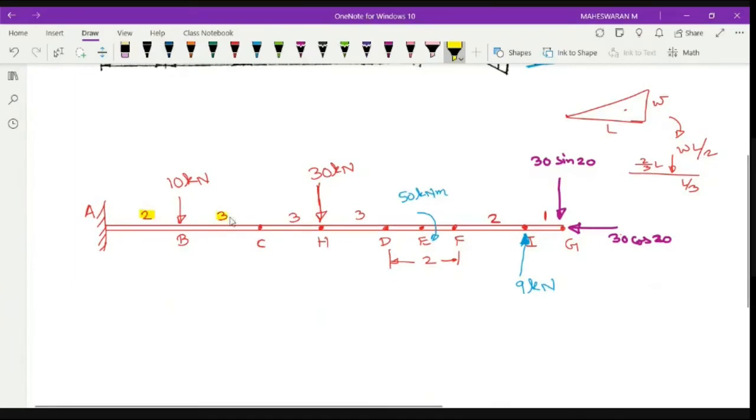Now, see, I have highlighted all my distances. And all my forces are also indicated in different colors. So once you have done this, then the part is over. Then we can easily solve this problem, right? Okay, you have a fixed support. When you have a fixed support, you know that you will have AX, you have AY, and you also have moment reaction, ME. All are applicable.